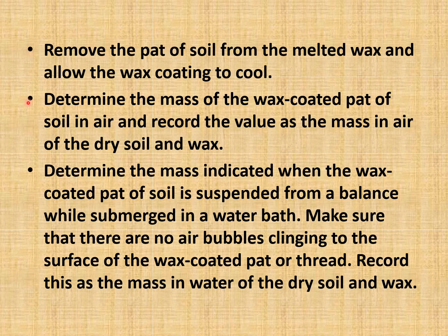Determine the mass of the wax coated pad of soil in air and record the value as the mass in air of the dry soil and wax. Determine the mass indicated when the wax coated pad of soil is suspended from a balance while submerged in a water bath. Make sure that there are no air bubbles clinging to the surface of the wax coated pad or thread. Record this as the mass in water of the dry soil and wax.